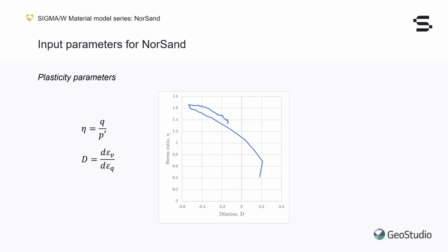On this plot, however, the first recorded dilation value is point A, which is already at a stress ratio of 0.4. This is simply caused by dilation being calculated as a change in deformation. Hence, it cannot be calculated on the first step of a test.